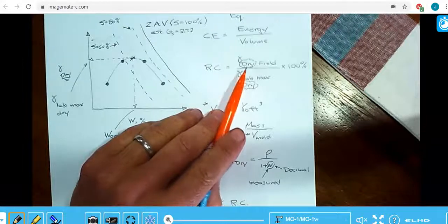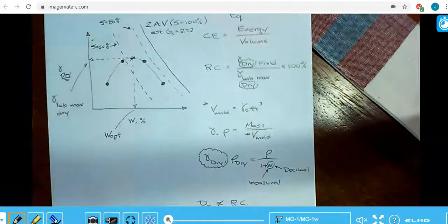If we did this activity that I'm describing, then we've just increased the total unit weight, right? Because now we have water in the voids. But we didn't do anything for compaction. We still have the same void ratio. All we did was put some water in the voids. Okay? Well, that didn't help reduce compressibility. So that's the reason why we don't compare wet to wet, we compare dry to dry.